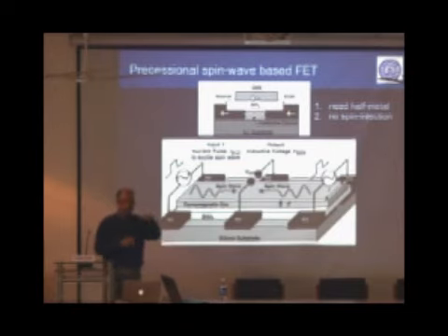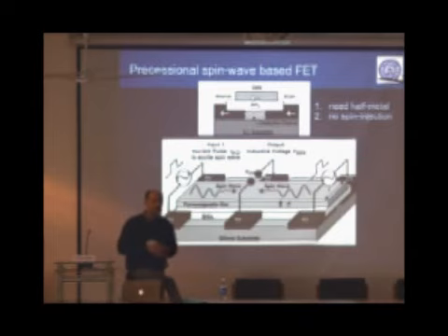So if you launch a wave in one direction and design it in such a way that you have another wave or line in this direction, the precessional logic signals in one direction versus the other will just cross each other. They will just superpose in a small region and then cross. So you don't need interconnects to route this signal from one end of the chip to the other. You don't have to go up and then down again through interconnects. So that's a good benefit of this sort of design.